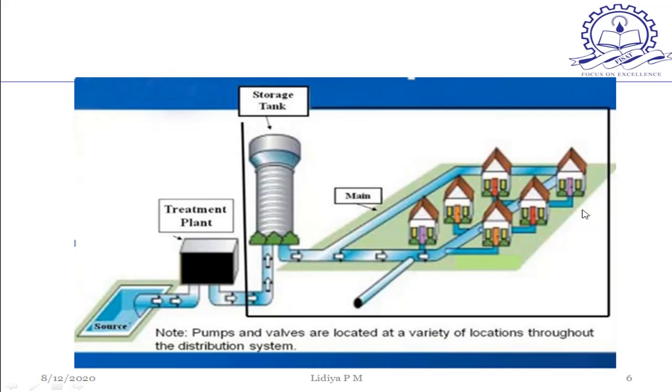It depends upon the area where we are distributing the water. We have to identify the number of households. Based on that, we have to calculate the water requirement of that area. Then the next step is the distribution system, that is laying of the pipes. In the design of the distribution system, we have to fix the diameter of the pipe, the type of material we have to use, then the pressure on the pipes. So all these components together constitute the water distribution system. So this is a part of water resource engineering.